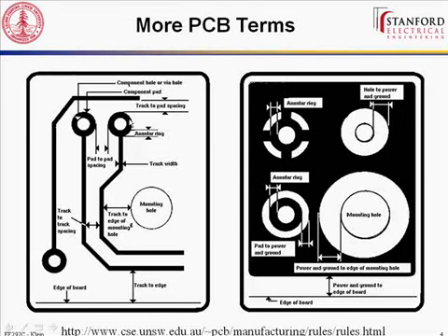Now up here in this left-hand part, you'll actually see these two holes that are going through. These are either holes for a component or vias. And you'll notice there's something around it with copper. You actually have to connect from that plated wall inside of the hole up to your layer, which is what's called the annular ring, and that goes around it. There is a minimum annular ring width, an increment on top of the original radius or diameter of the drill. A lot of times this will be at least 5 to 10 mils, depending upon your process.